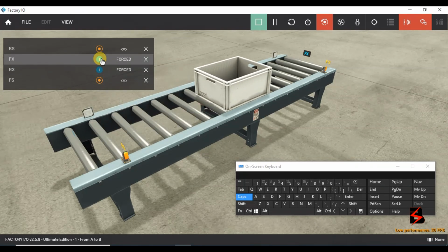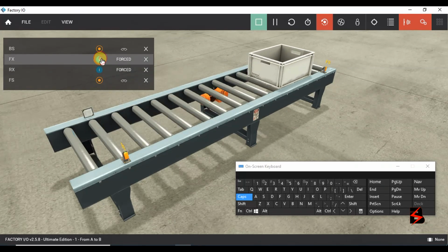So the routine is going to remain like that, until the stop button is pressed. That is automatic mode. So you are going to have an HMI that is going to help us detect the sensor states, to monitor the sensors. Then have manual control, that is forward, reverse, and also have automatic control, that is start and stop.